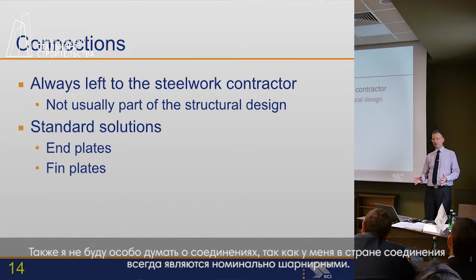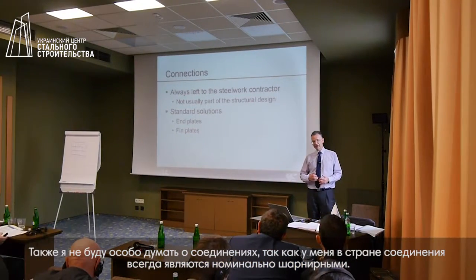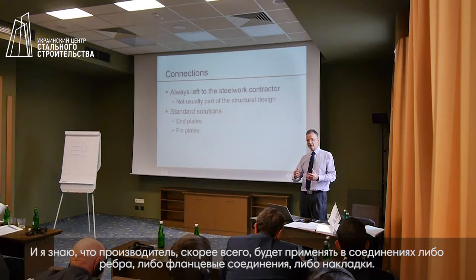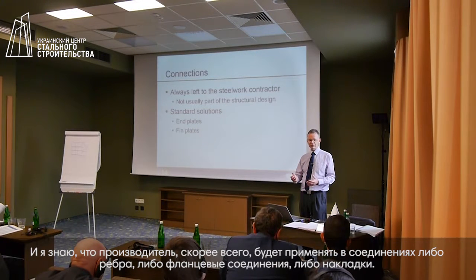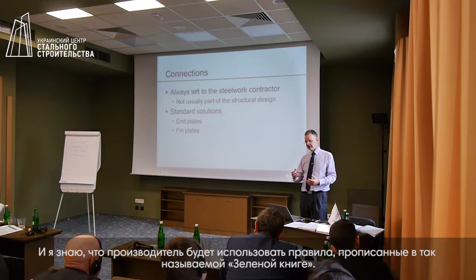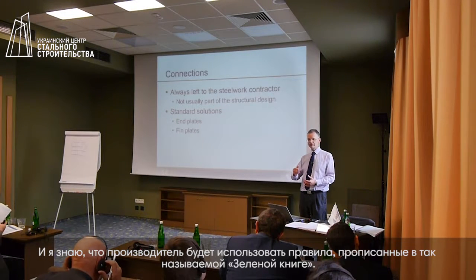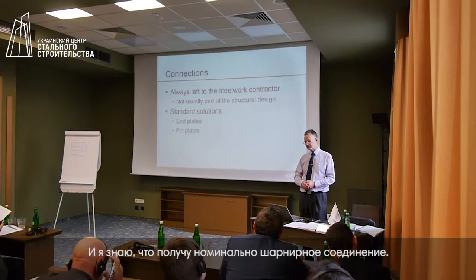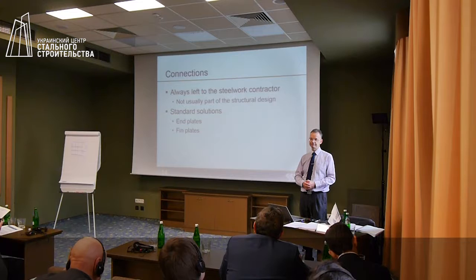I would not concern myself with connections, because in my world, the connections are always nominally pinned. So I know that the fabricator is going to choose perhaps a fin plate or perhaps a flexible end plate, and I know that he will be using the rules in what we call the Green Book, which is a book of standardised connections. So I know that he's going to deliver me something which behaves as a nominal pin.